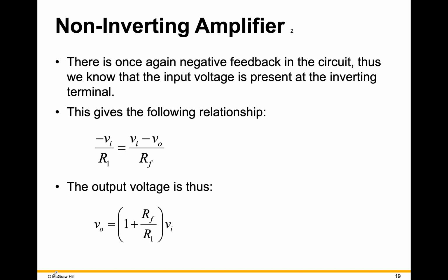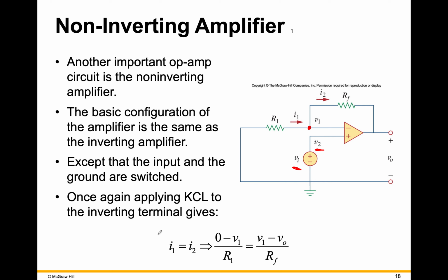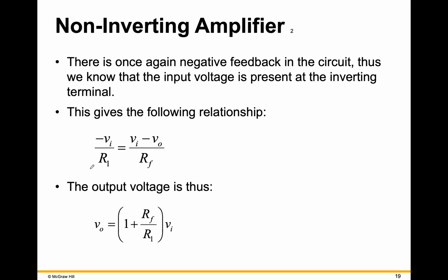First, you get the relationship that we found here, which was applying a KCL equation to the inverting terminal, and then you can write a KCL equation or a node equation right here at the output terminal. If you do that, you get this relationship. Okay, so combining those two equations and eliminating some variables, you get this expression that puts your output in terms of your input.